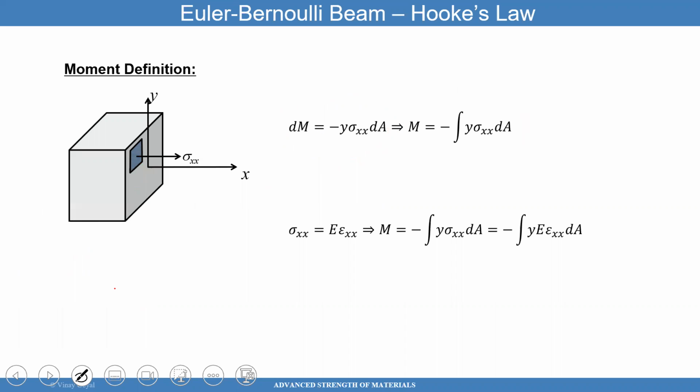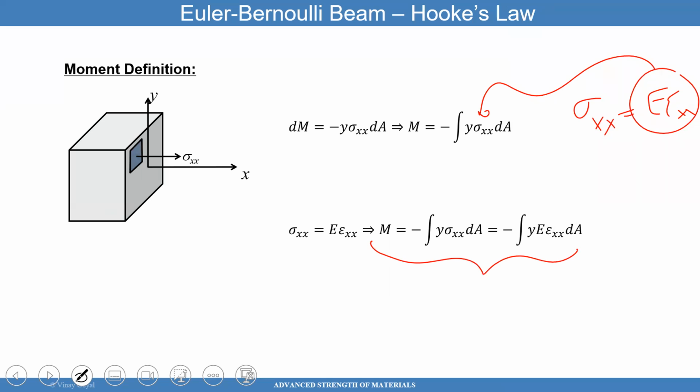But guess what? We all know that stress equals E times strain. So I plug that in here, and I get the moment equals the integral of minus y, the modulus, the strain epsilon xx dA.